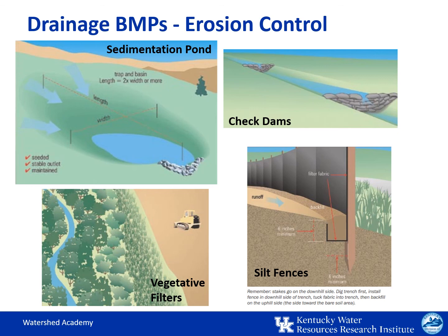Finally, vegetative filters are temporary or permanent sediment traps of cultivated or naturally occurring vegetation. These are also familiar to you as riparian zones, grass filter strips, and stream buffer zones. They provide areas for the deposition of runoff pollutants before they reach the drainage ways. In mining areas, these are best employed in areas of moderate slope that receive sheet flow from storm events.